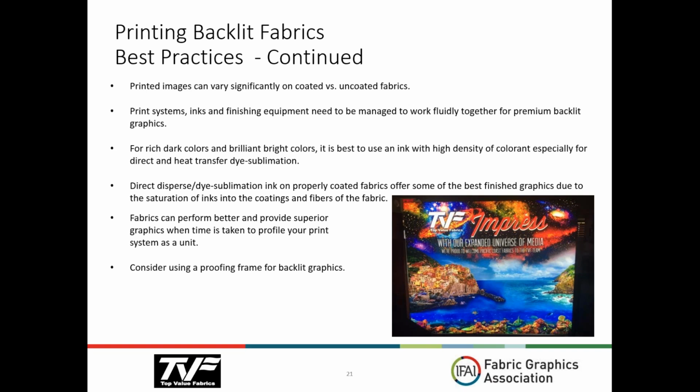Now, some lighter weight fabrics that aren't coated, you wouldn't do that with, because you run the chance of actually turning the fabric a little bit brown or off color. But in this case, it makes a tremendous amount of difference with your ink saturation and the finished product. So fabrics can perform better and provide superior graphics when the time's taken to really profile your entire print system as a unit. You can even have two exact same printers with the exact same ink side by side, and the print results can be different.